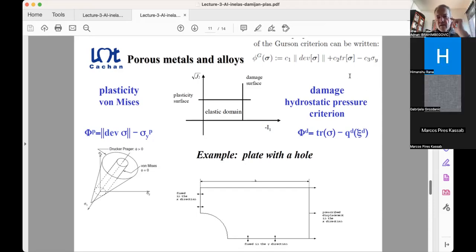If you look only at plasticity, that is one case, but if you now take the pores filled in with damage, you come back with the damage criterion, which is proportional to the trace part of the stress. And then this is your classical J2 plasticity. Then the elastic domain becomes very simple, it's rectangular in the space of the square root of J2 and the I1 invariants. So it becomes a rather simple computation that we're able to carry out and get these results.